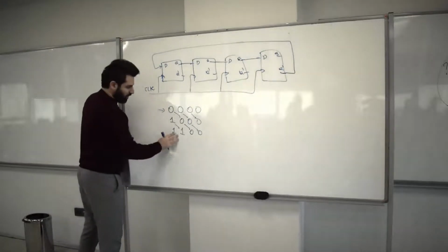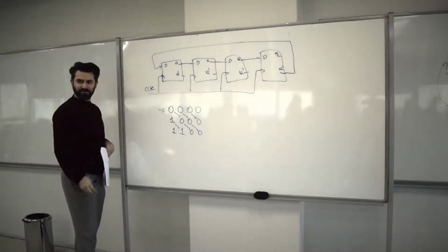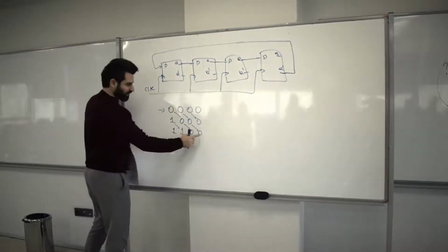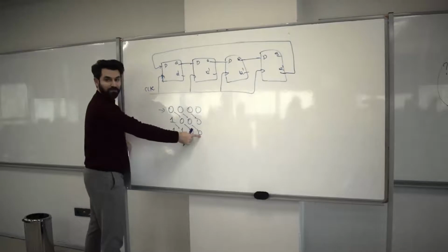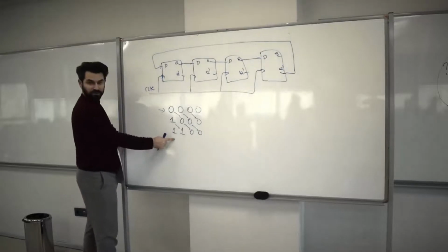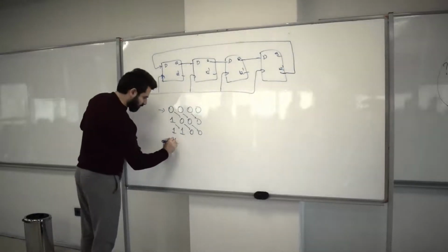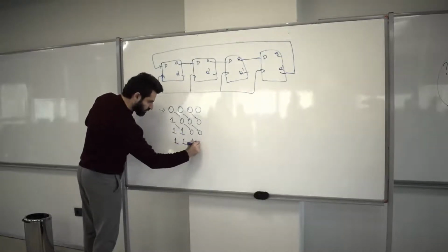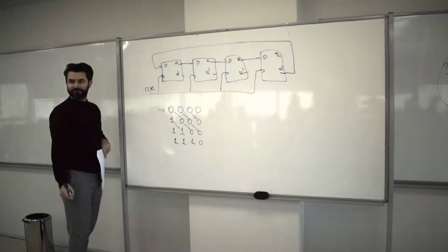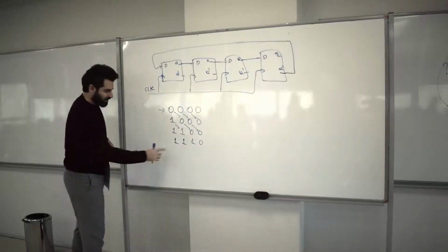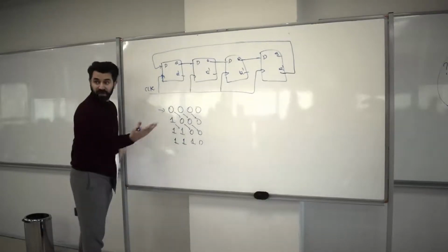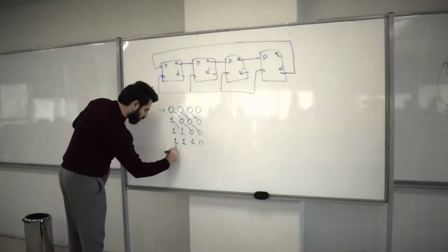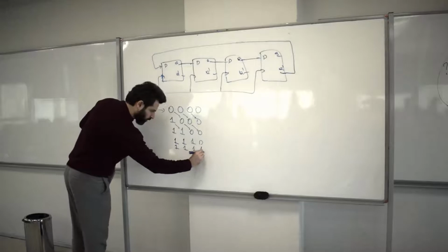Now I've got 1, 1, 0, 0. Is everybody happy with that? Questions? We good? Okay. So now we've got 0 here, which is going to make it 1 again, and that 1 is pushed into the circuit. So you're going to have 1, and those 1, 1, 0 are shifted to the right. You get 1, 1, 1, 0. In the next clock cycle, this 0 now becomes 1, and you push that 1 in from the beginning. You get 1, 1, 1, 1.